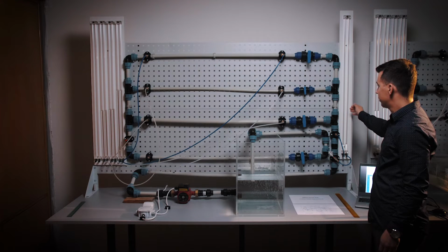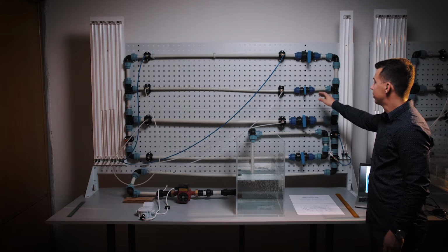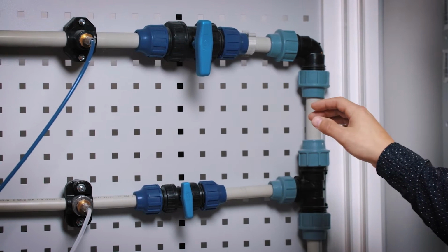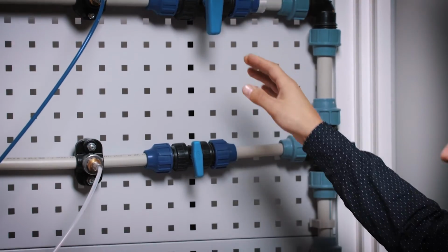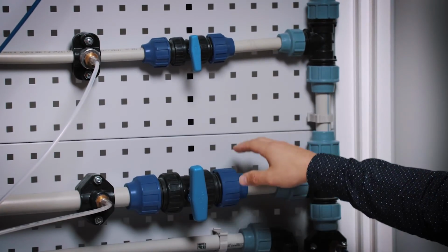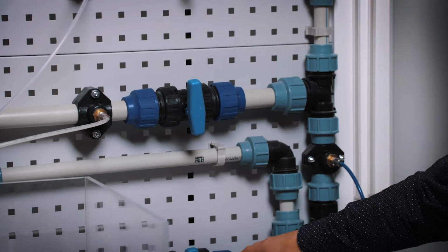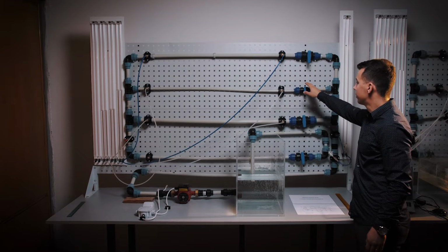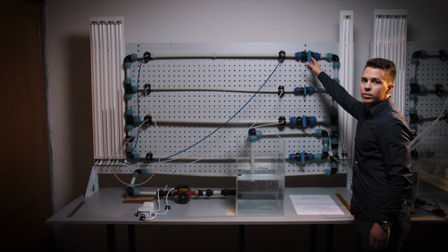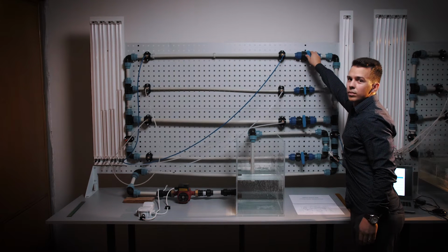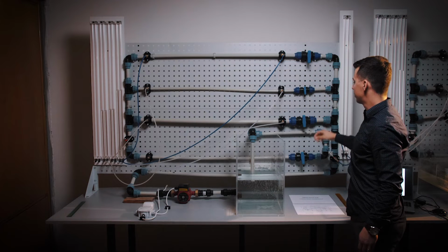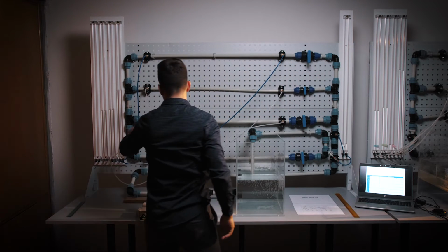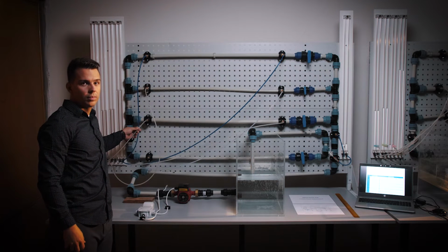The hydraulic circuit contains 4 measured pipe sections of the same length and of different internal diameters. From above: 18, 14.4, 23.2, and 18 millimeters. Each section is equipped with a ball valve at the inlet, which can close the flow through a specific branch. We take pressure samples at the beginning and the end of individual sections, and the distance between tapping points in all cases is 1 meter.